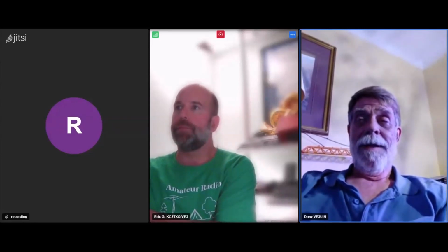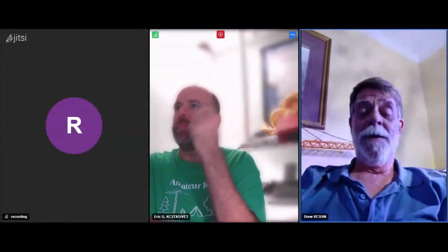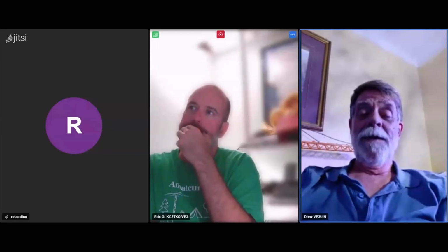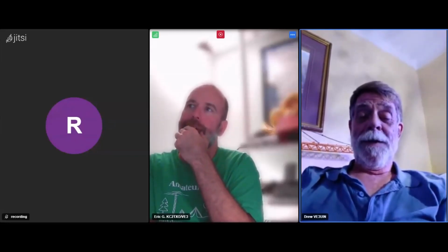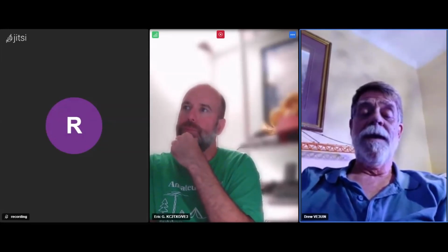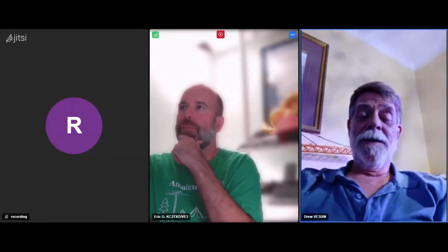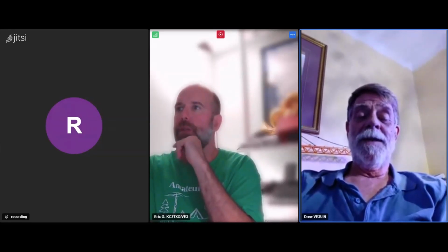But would it give you a warning? Like, let's say you have nothing... No. Apparently, it's a poof. Wow. Oh yeah, I've been reading all these horror stories on the web. I'm going, well, that's encouraging. So now I'm building a match. Well, you can't even measure SWR at that power. The meter won't read. So you've got to use something else to match the antenna, and then you hook the radio up to it.